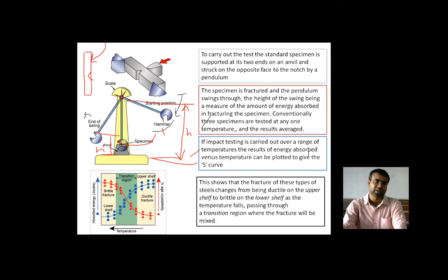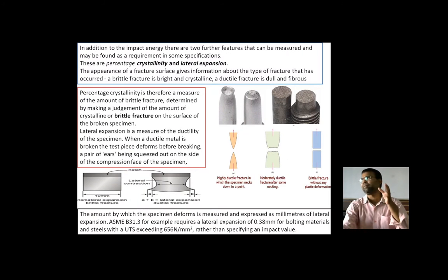When the material does not resist, it will start breaking, and on breaking it stops the hammer from moving further upward. So that is how that height shows the energy that the material has absorbed, and that is how this test is taken. It is that simple. There is no complication in that. After the test, there is a lot of analysis to be taken care of, and there are various scenarios taking place during the test also. That is how it is defined.